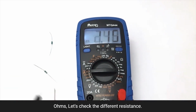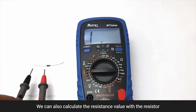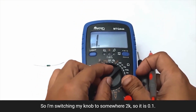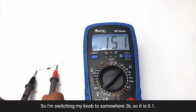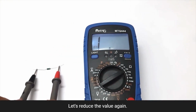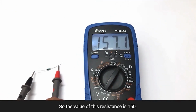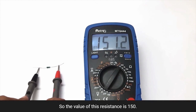Let's check a different resistance. We have this resistance here. We can also calculate the resistance value with the resistor color code, but as we have a multimeter, let's check with the multimeter. So I'm switching my knob to somewhere at 2K. So it is 0.1. Let's reduce the value. Again it's 0.2. Let's shift it to 200 ohms. So the value of this resistance is 150 ohms.